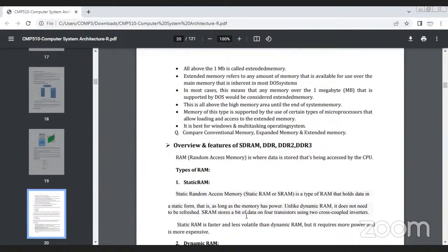Okay, so next part is DRAM. DRAM is a dynamic RAM. Dynamic RAM stores the binary information in the form of electric charges applied to the capacitors. The stored information on the capacitors tends to be lost over a period of time, and thus the capacitor must be periodically recharged to retain its usage. The main memory is generally made up of DRAM chips.